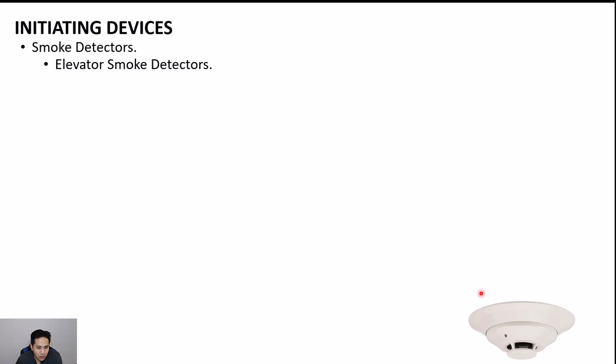If there is smoke on the 1st floor, which is the level of discharge, then it'll go to a 2nd floor, or basically an alternative floor, which is probably going to be the 2nd floor, and it'll basically open up there and stay open, and the elevator will not be able to be used by anybody else in the building.